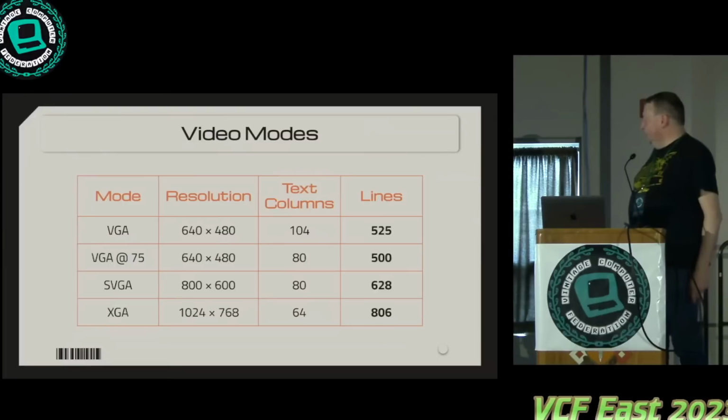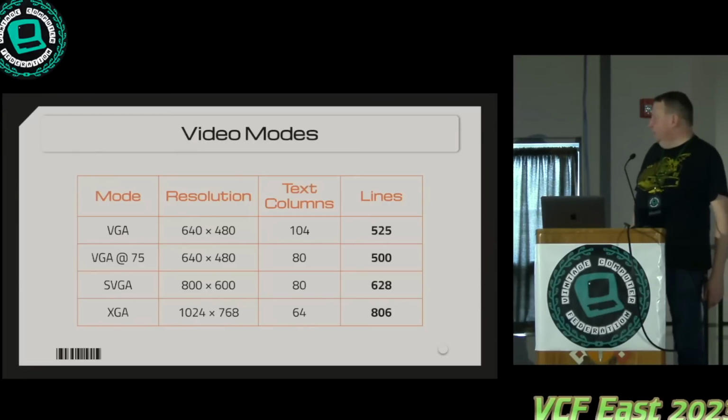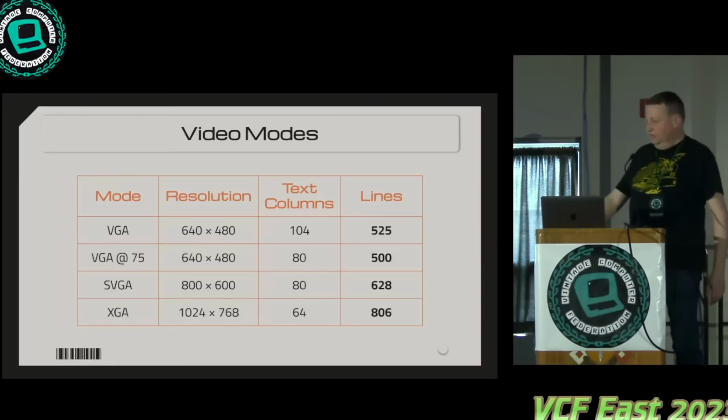It actually supports quite a few different video modes. So VGA, 640 by 480. There's a 75 Hz version, SVGA, and also XGA. Now I have a fixed dot clock, and that's closest to this VGA at 75 Hz. So if you do it at 60 Hz, you actually get 104 columns of text. And the Super VGA, which technically would be 100 columns of 8 by 8 glyph text, you only get 80 columns. And then this XGA mode, you've got a lot more rows, and you're down to 64 columns. But you can actually run CPM on 64. And these are the actual total lines for the video frame.